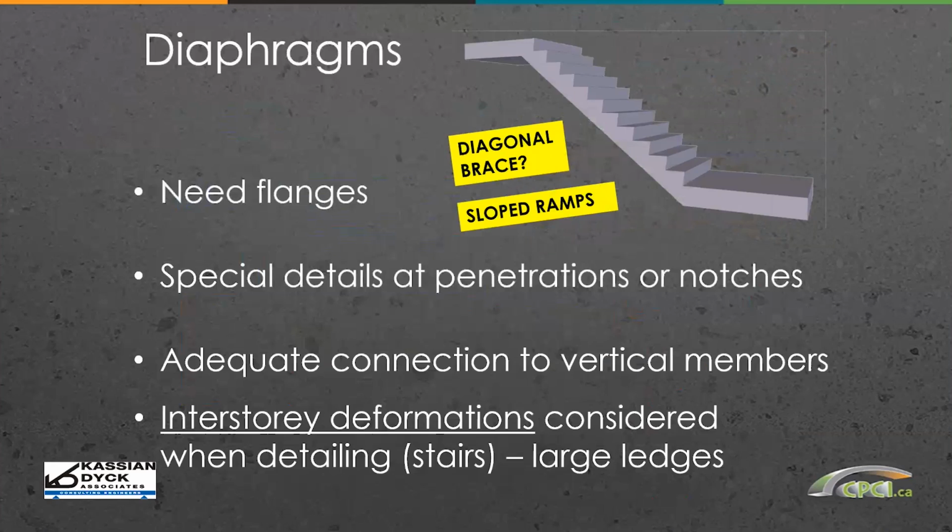They're going to potentially act as a brace member because they're on that diagonal. So if they're there, they're potentially going to attract load if they're connected top and bottom. If one end is released, then they may be able to move and not attract load going through the stairs as a brace, but it's something you need to consider as a structural engineer.